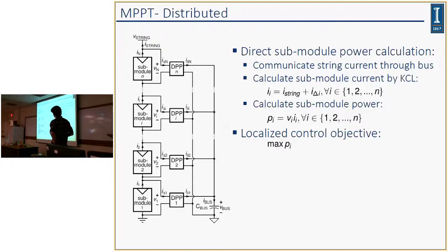Now all it needs is this current right here to be able to directly calculate the submodule current. That's not a huge trade-off, because the amount of current here is usually pretty small. This just leverages the fact that in DPP that current is usually small. So the amount of loss incurred from using a resistive current sense amplification would be small as well.